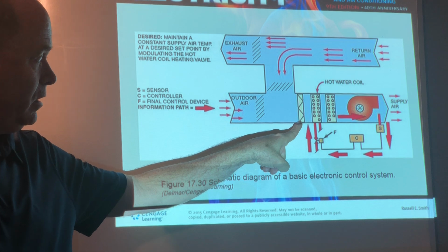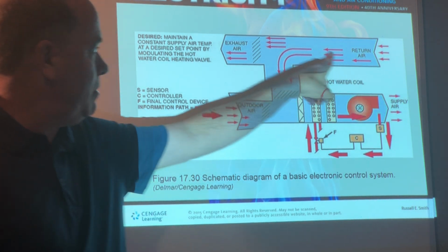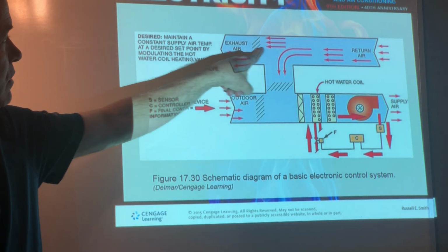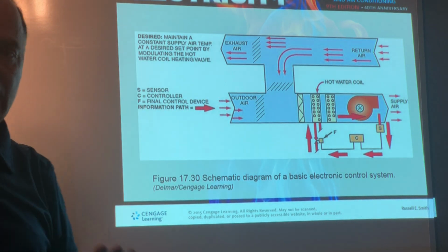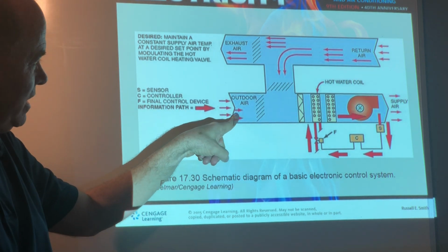and that's what this is. This is your air filter. Here's your return air coming back from the space, from the building, and then we can either exhaust some outside or bring it back. Let's say you're in a minimal outside air situation, 85% return air, 15% outside air.